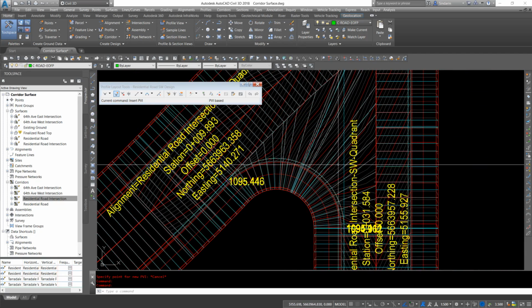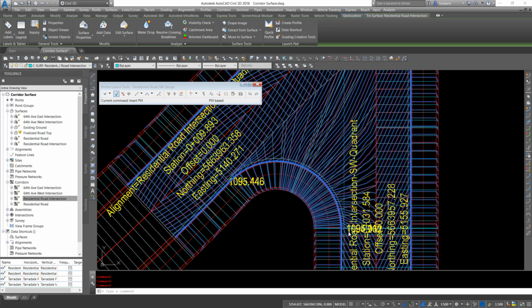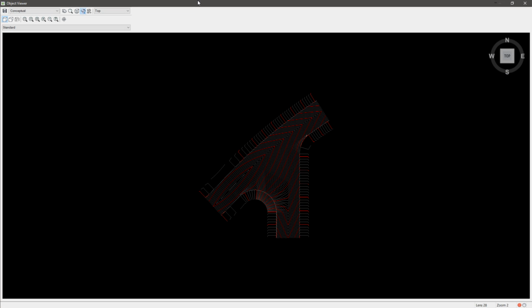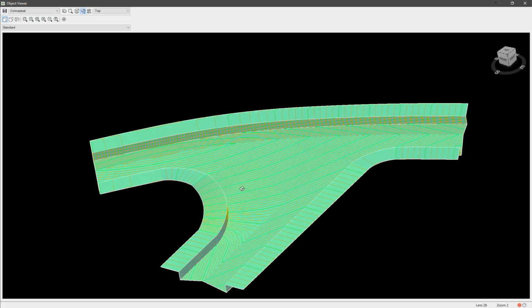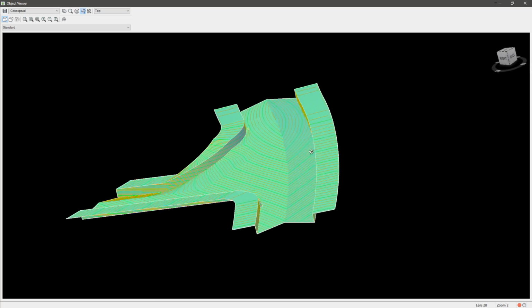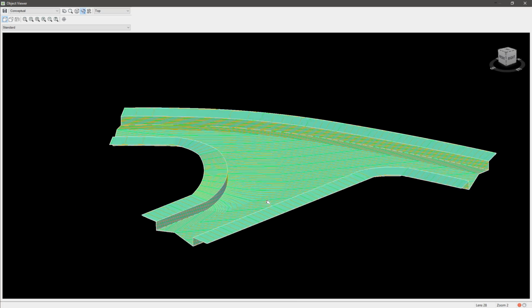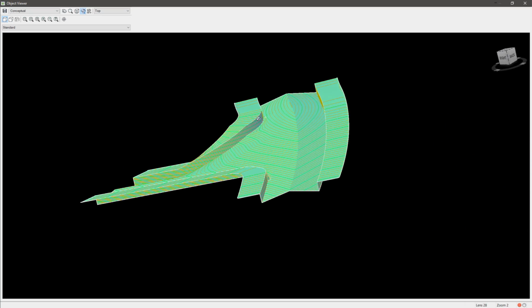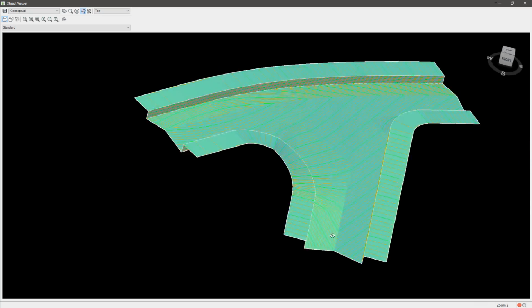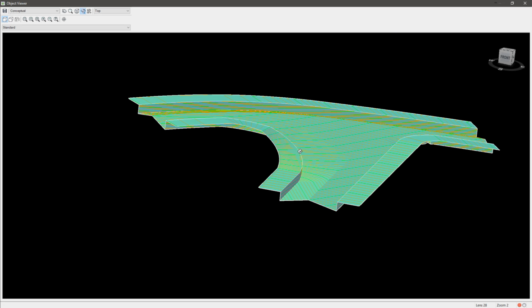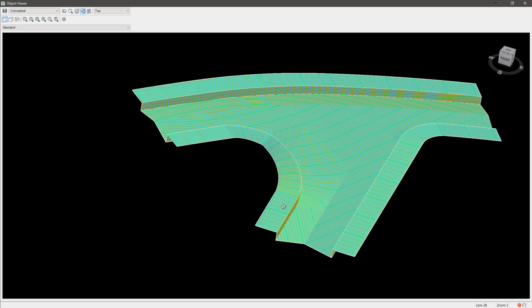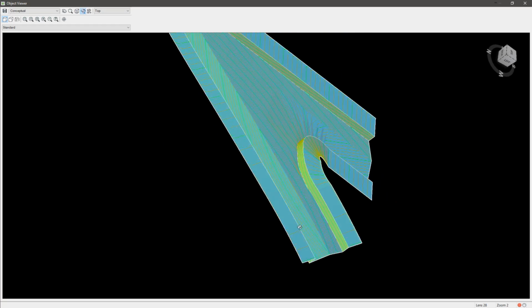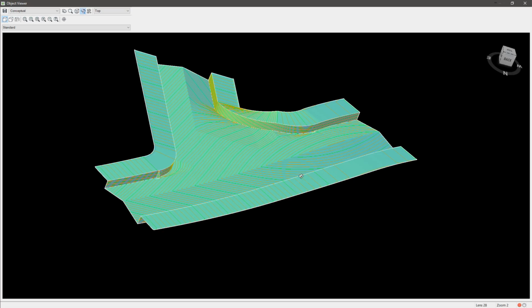Let's put a little bit steeper around the corner. So again, just a quick object viewer to see what it's looked like. And adding that PI in has made it look a lot better. So again, the angles of the road and the steepness of the terrain is my best guess at what has originally caused this issue. Civil 3D just had a hard time trying to solve it.